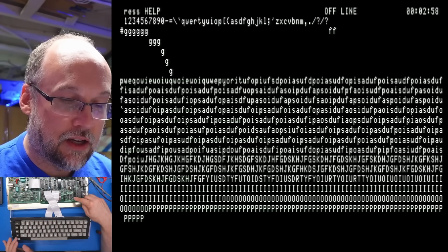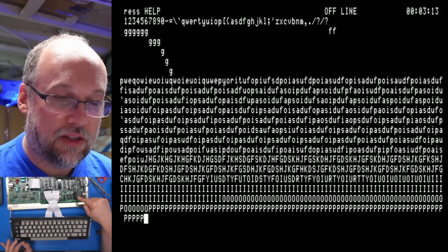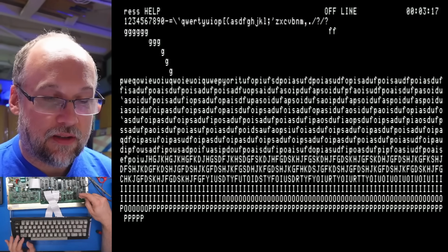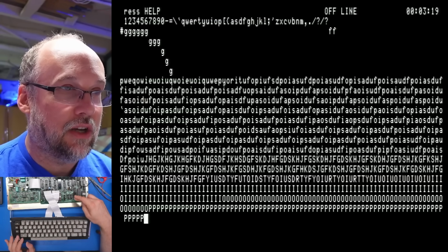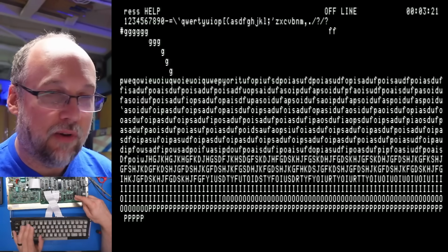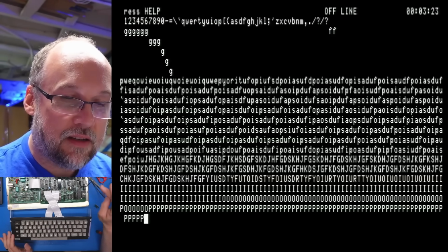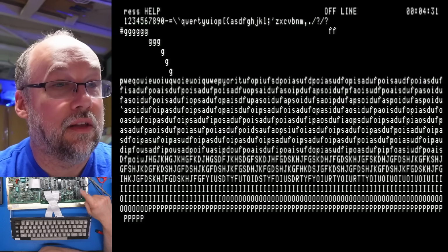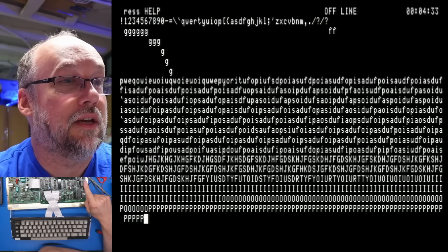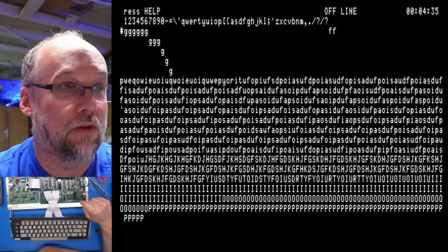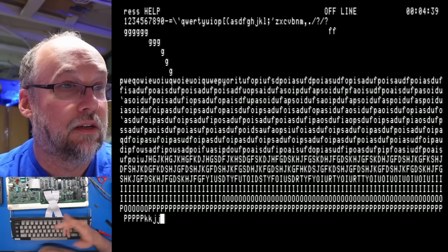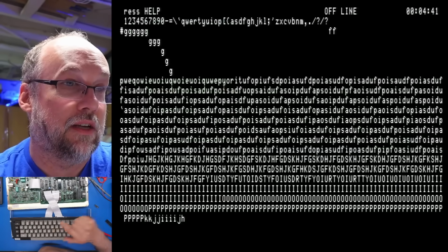I feel like either the SRAM itself is a problem, or the Siemens variant might be slightly incompatible with the Intel. It is the video chip on this that actually goes through and reads out the contents of the SRAM based on the parameters you configure on it, that then gets displayed to screen. Oh, look, the glitching just started again. I think this could be a RetroTink incompatibility, so I would need to plug this into something else just to make sure that it's not that causing the glitching, because there doesn't seem to be any other issues, like the computer's still responding at least when I type.